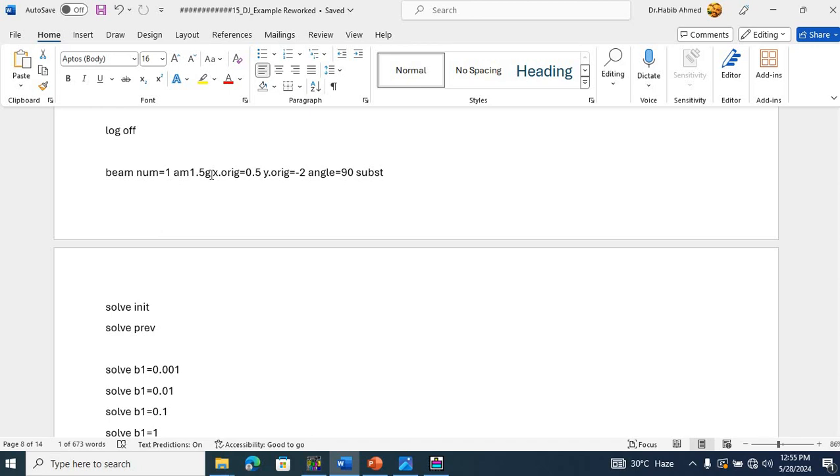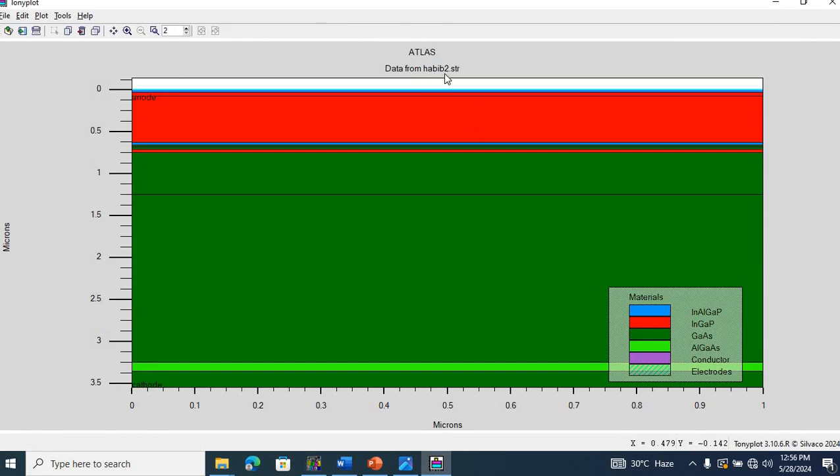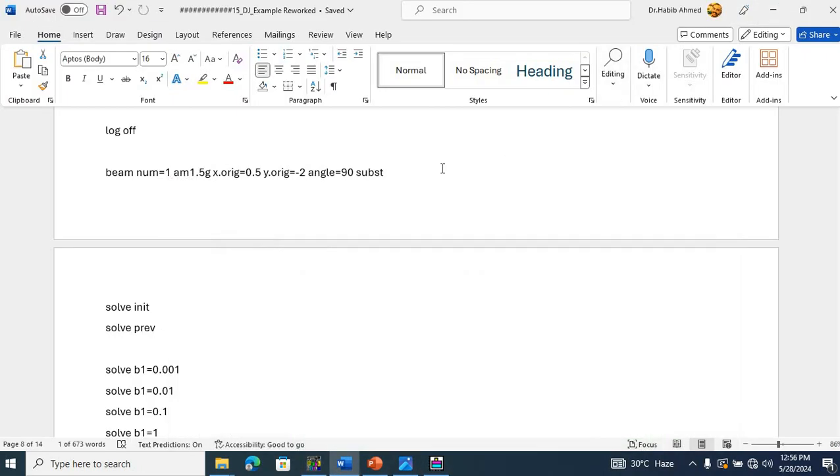As you know, that is 1000 watt per meter square, or conversely 100 milliwatts per centimeter square, at room temperature, 48.2 degrees angle with respect to zenith, or with respect to the vertical direction, and it originates at minus 0.2 in the y direction, so slightly above the structure, directed downwards.